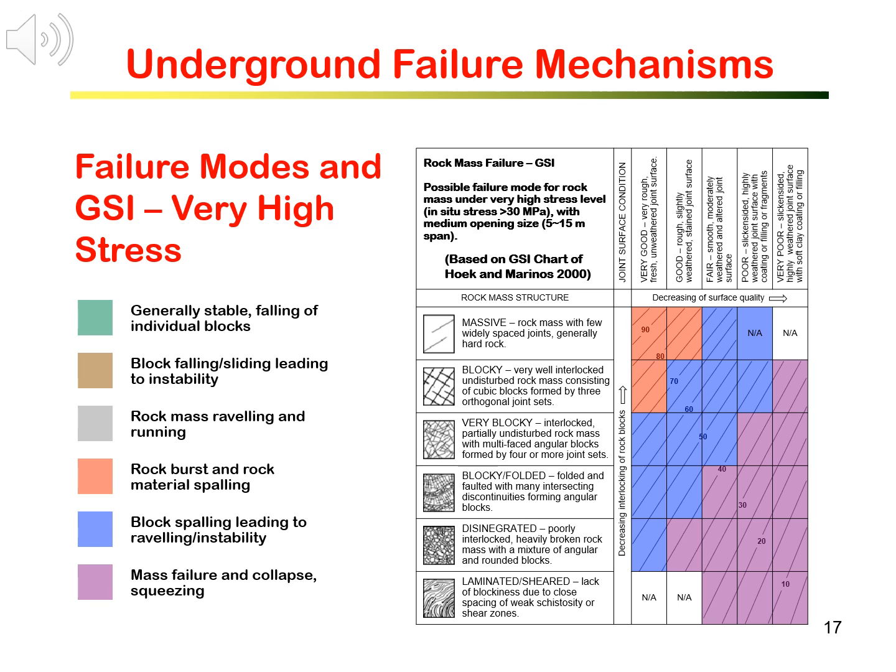In addition to small block instability, very high stress may lead to the spalling failure we saw in the photo earlier. To the worst extent, rock burst may happen.